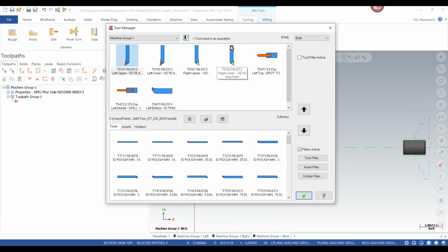the locator positions are at the back of every tool for a turning holder, and for a drill, it's going to be the back of the actual holder. So this is a combination of the holder definition and the drill length itself. On the boring tool, of course, it's just the total length of the boring tool.